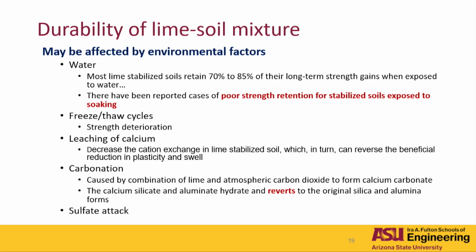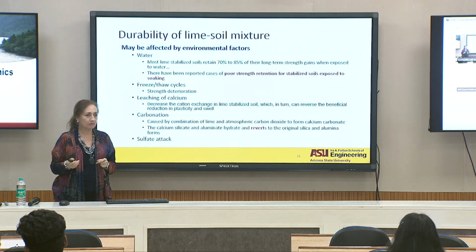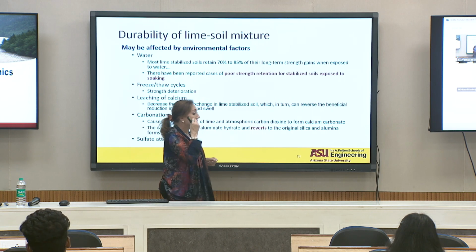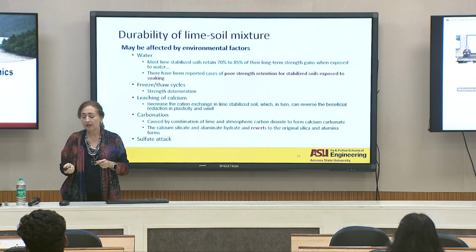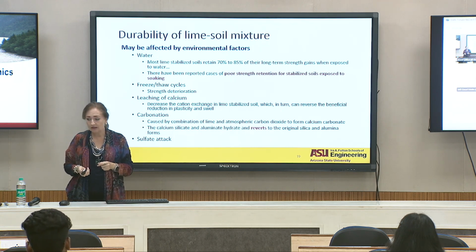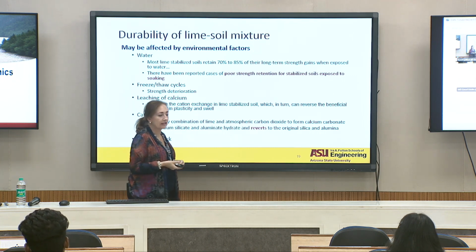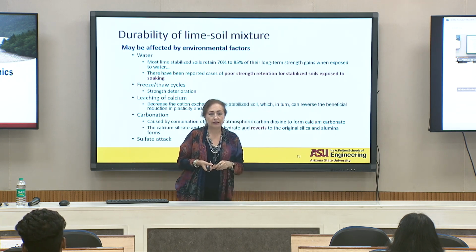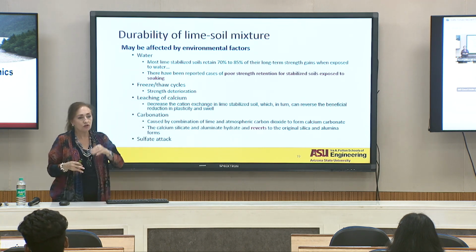The durability of the lime soil mixture, and I focus on lime because this is the main mechanism that we use for expansive soils, may be affected by environmental factors. Water is one of them. Most lime stabilized soils retain their strength in the long-term condition. But when they get exposed to water, there have been reports of poor strength retention for stabilized soils exposed to soaking conditions.